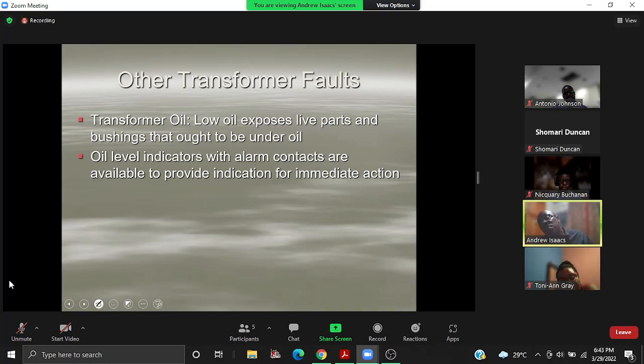It requires some attention. But once you get to low oil, it means that you are now exposing the windings, and it needs to be attended to immediately. So you have those indicators. All right?